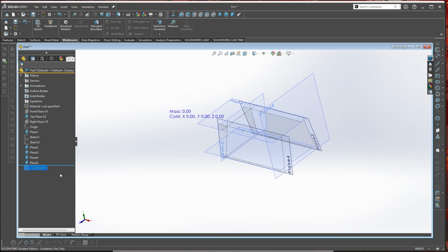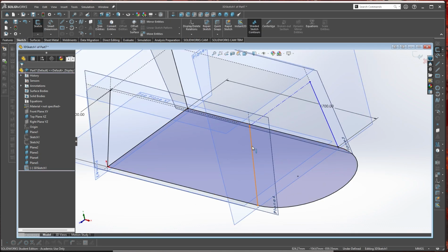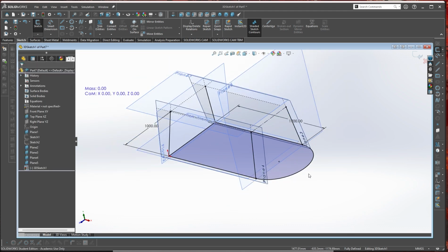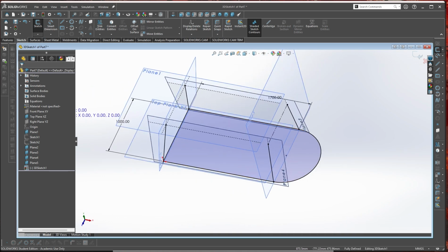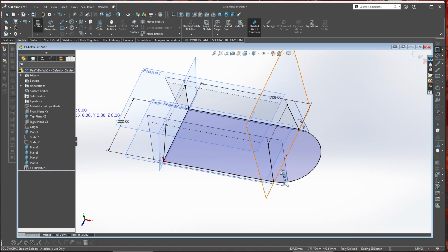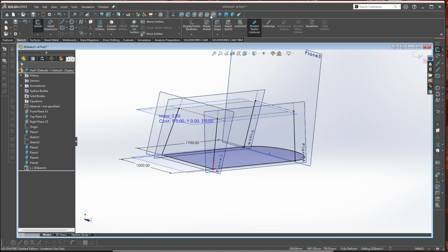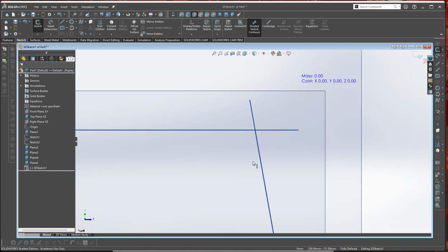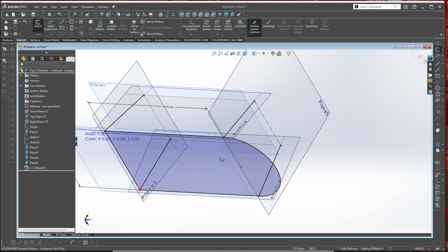Okay. Turn the sketch back down here. Now we're going to take this and this and put that on that plane. So here is the fully defined true framework of what SolidWorks is expecting when it comes to these measurements. Simple little problem, but a little bit exaggerated is kind of the approach here. Okay, so everything is on plane at this point. If we move to our back view, left view, as I scroll in, you can see that everything is nice and lined up now. There's no discrepancy between those. But most importantly, let's lock up the rest of this.